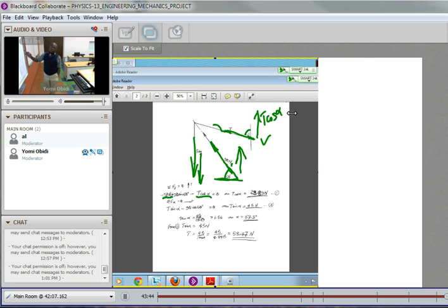So in equilibrium, because when you're studying, you hold your head in that position. The head doesn't dance around, so it's at rest in that position. It's maintained at rest by the force in the muscle, by the tension. You know, a little headache may come along the way, but you keep that head in position so you can focus on the study. So it is an equilibrium situation, and this is the tension in there, and this is the y component of the tension. This would be the x component of the tension that's on the back of the neck. So we set up those forces.